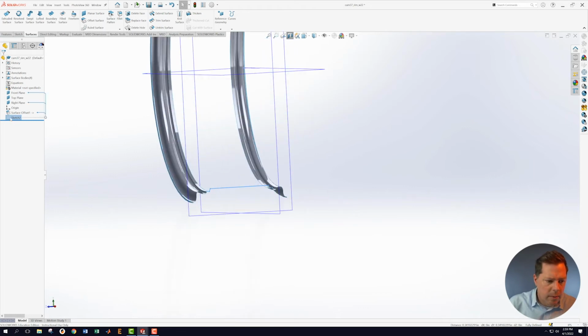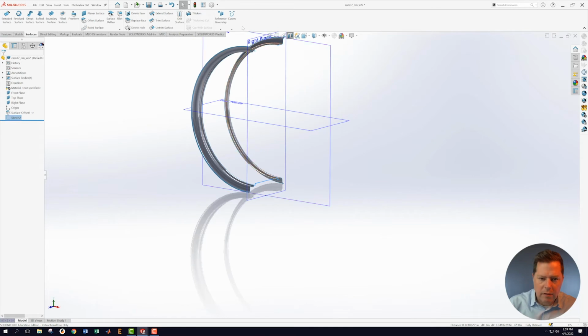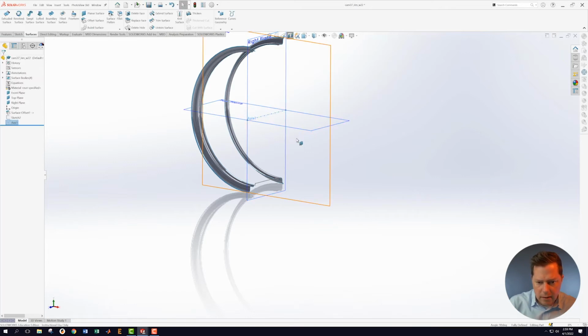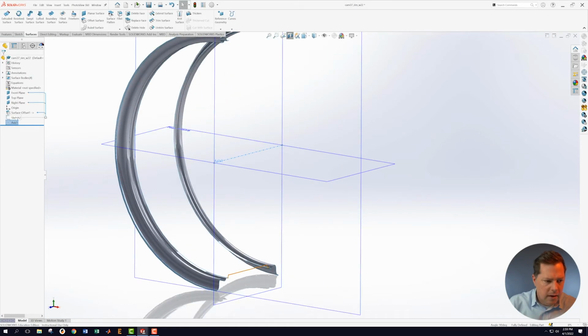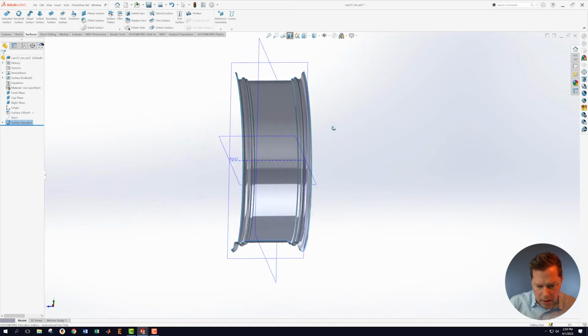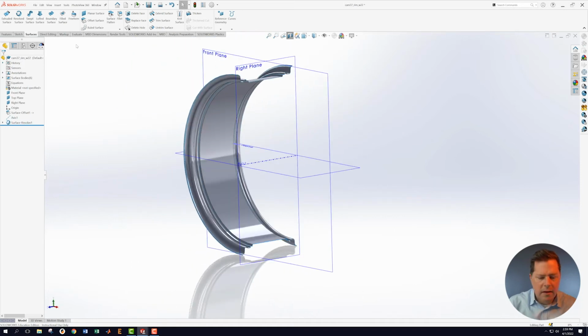All right. Excellent. I should be able now to take this sketch and revolve it around an axis that's not in here yet. This axis and, well, that yellow axis that's right there. Okay, let's take sketch 2 and axis 1 and do a surface revolve. Just that one. It's looking good. Okay, excellent. That is the part of my rim that matches my tire.